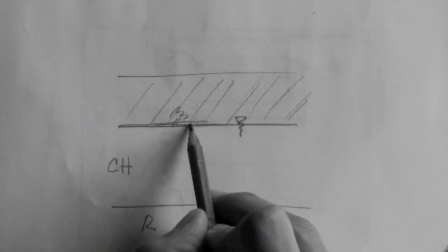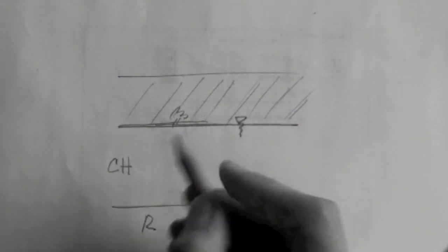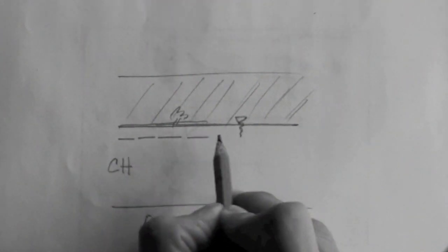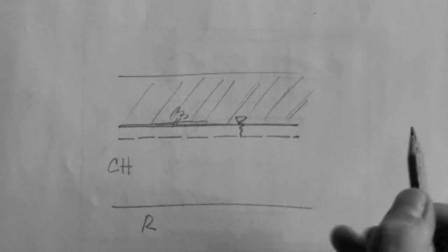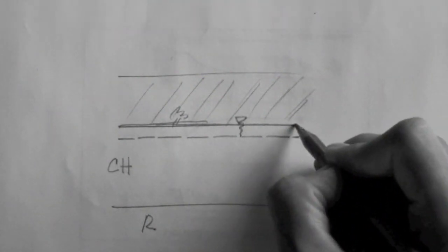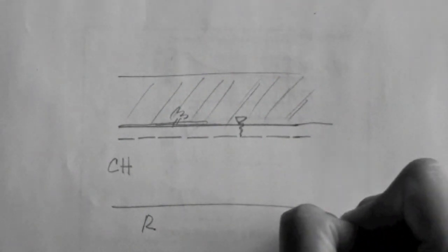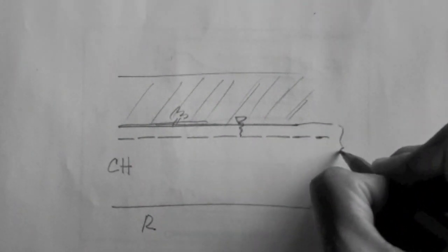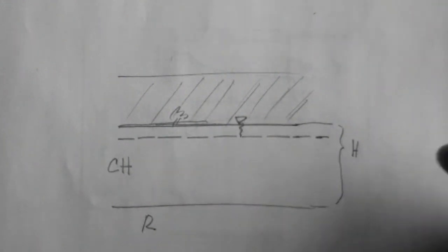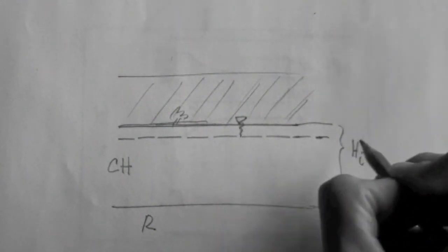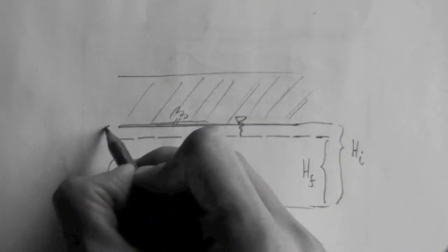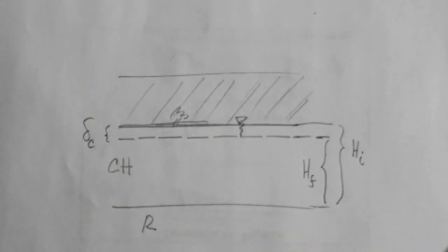Now, eventually, the layer is going to end up maybe this thick, okay? So the initial thickness, which is denoted typically by H_i, is that, and then the final one is that, and this is the consolidation settlement, okay, which we're going to learn how to determine later on.